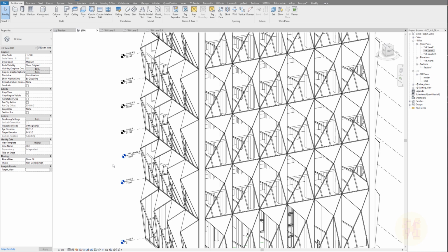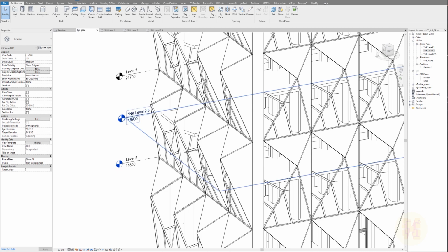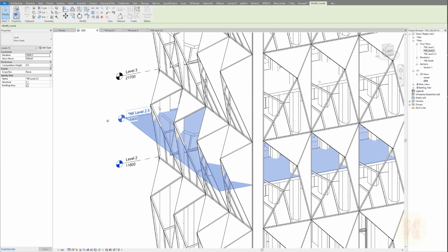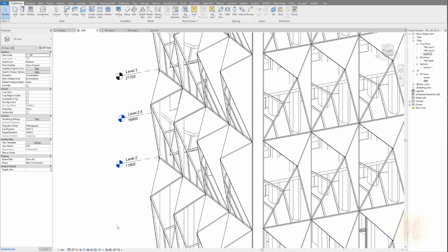The other problem you can see right now, when we change the naming of the level, is not good for us. We should keep the level naming. So if you delete this name, Revit asks, would you like to rename the corresponding view? Yes, I want to change the name. If you change it, as you can see, the view name changes too. So how can we work with that? If you are changing the name of the level and also changing the view, how can we manipulate that? Actually, the secret is really simple.